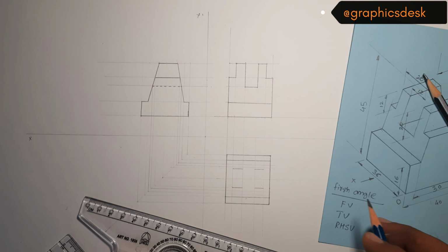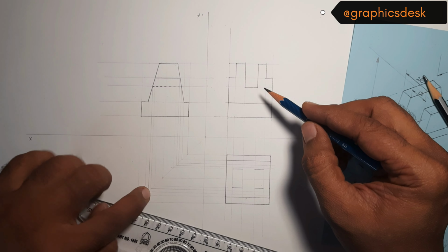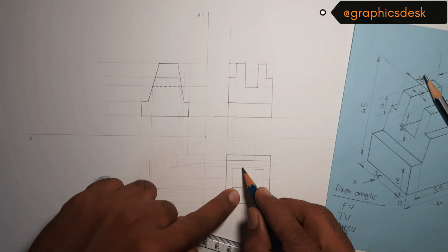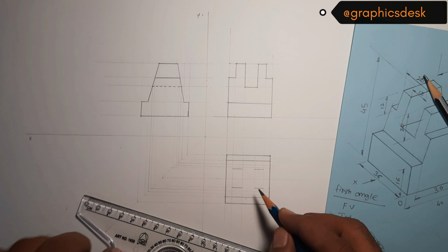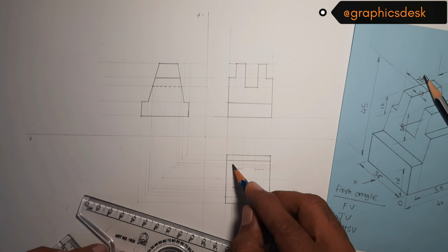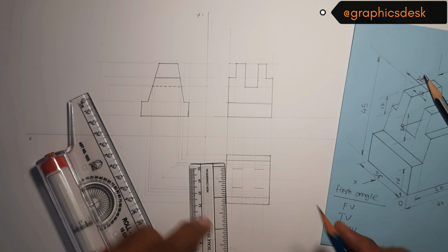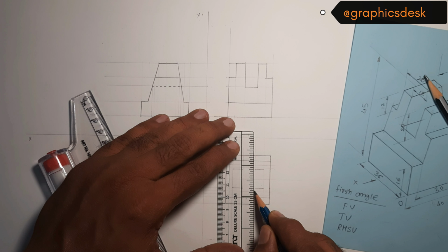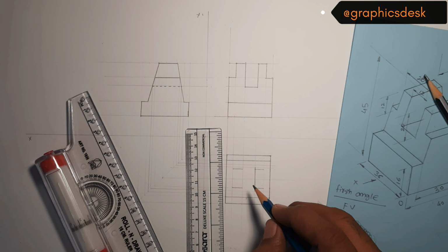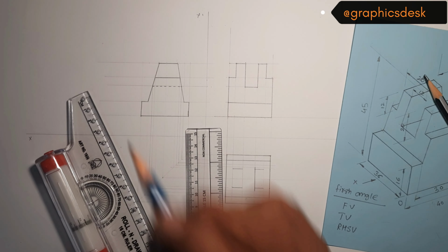Now the extent of this particular object, so this is where the dotted line is coming up until this point, which means this particular section inside the diagram would be visible. That means I'll have to draw a solid line over here and a solid line from this point like this. So let me draw that. That will give you a visualization of the object. Now, as these points are on the slant surface, we had to carry the projections from the right hand side view.